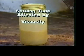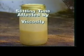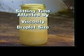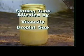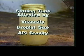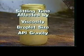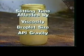If the oil has a high viscosity, that is, it's thick, then the water droplets cannot move around easily and will not settle out quickly. Settling time is also affected by the size of water droplets. Smaller droplets are lighter and take longer to separate from the oil. If the difference in API gravity between water and oil is small, then separation is slow. However, water weighs more than oil and will eventually settle out if given enough time.